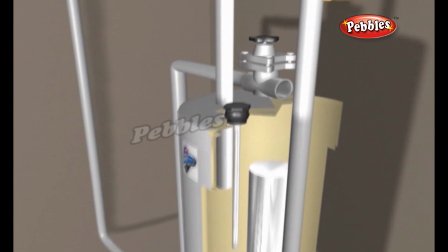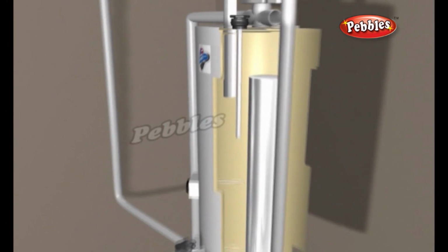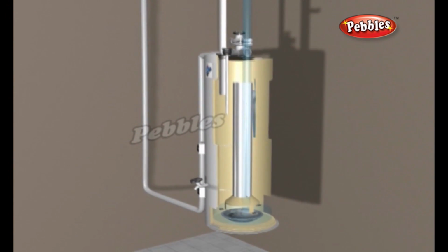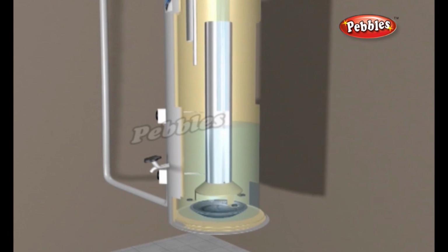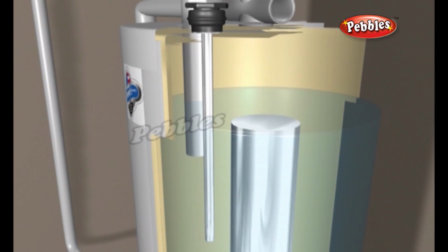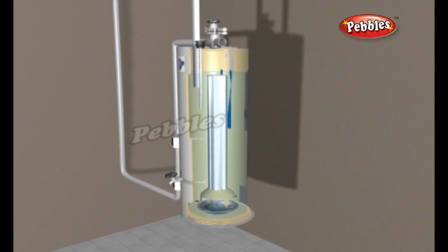The cold water supply line connects to the water heater, typically on top of the appliance. Instead of dumping the water on top of the hot water in the tank, a dip tube carries the cold water down to the bottom of the tank. The outbound hot water line takes the water off the top of the tank. That way, when hot water is drawn out, it is at full temperature. Only after most of the hot water has been used do you start to get the hot and cold water mix.